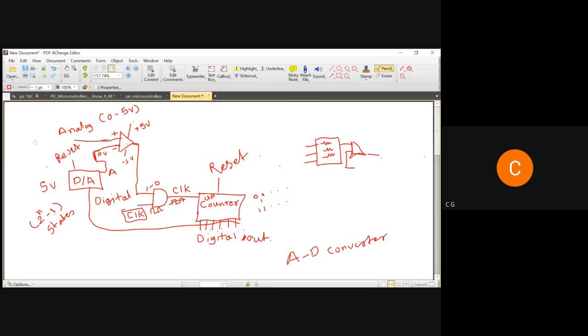You have to start from the analog input where the comparator is comparing the signal. Since this input is very high, it saturates to high level. This is like a Schmitt trigger. The op amp is working like a comparator or Schmitt trigger. The moment the input value changes relative to this reference, it will go either very high or very low. When it is negative, this is like 0, and this is an instantaneous reaction. Whatever is coming, it will immediately switch to the higher value. It has only two states now, very high or very low, negative.